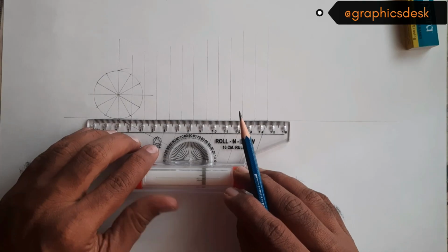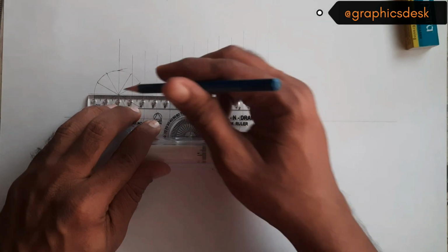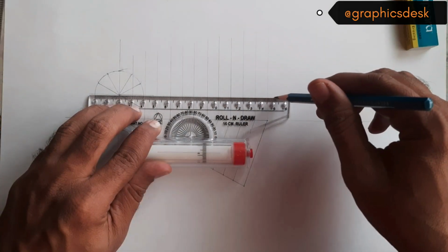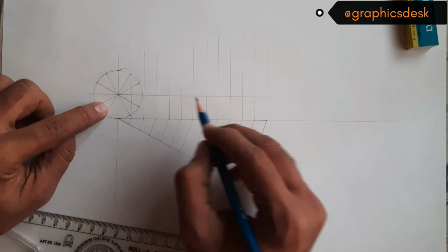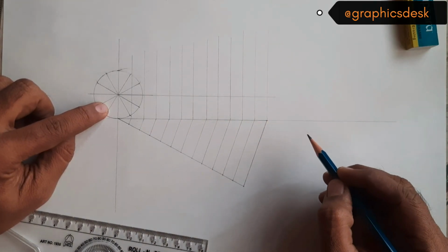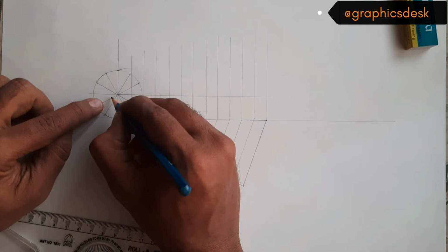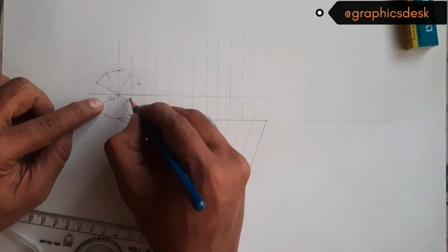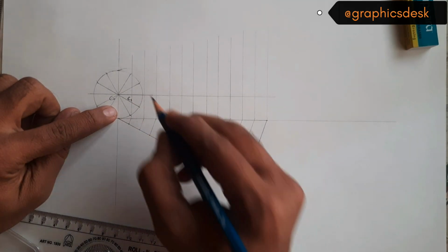And a horizontal line passing through it will connect all these 12 lines here. So during the rolling of this circle, the center lies at these different positions at each 1/12th period of rotation. This is C0, the starting position. This is C1, where the center would be after 1/12th of rotation.